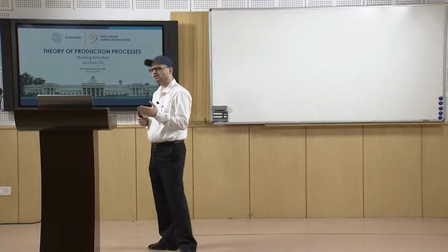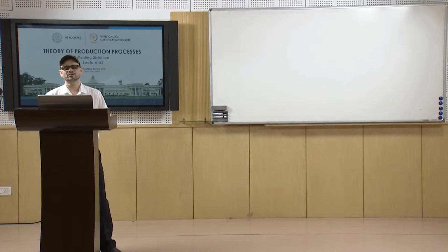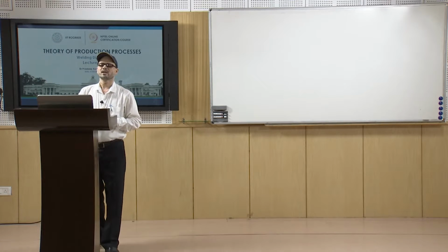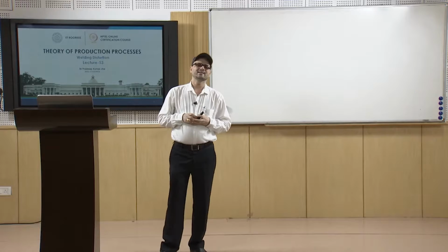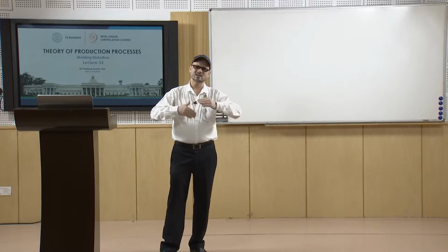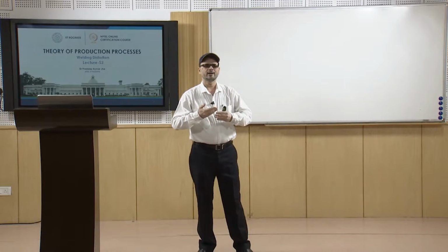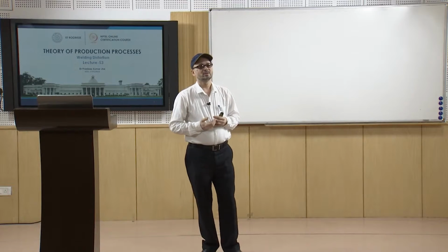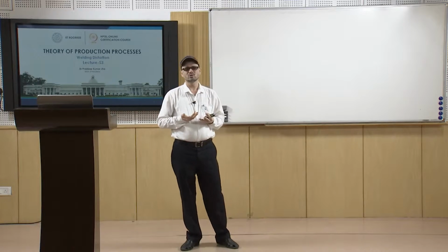The property which is primarily important for deciding such distortion is the coefficient of thermal expansion. If the coefficient of thermal expansion is more, then as the temperature changes, the expansion or contraction will be more. Once that is more, it means the distortion will be more.